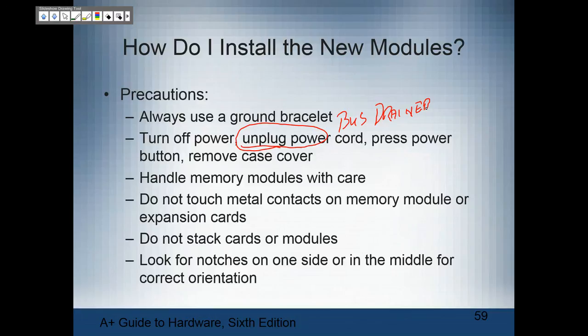Press the power button after you turn the power off and unplug the power cord. The power button will help drain the power that's held in the capacitors off of the bus. Handle memory modules with care.